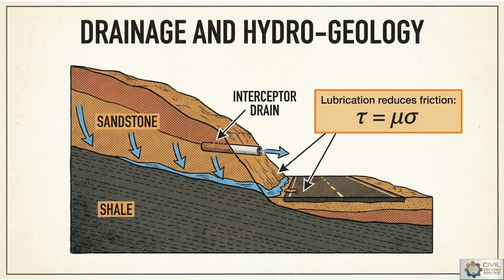So from the drainage and hydrogeological point of view, we can also study the type of rock, just like sandstone and shale, so that the water percolating through the sandstone may show capillary rise or capillary fall action. Shale does not. Shale is a hard rock with reference to sandstone and can't allow the water to enter it, so the water which seeps or percolates through the sandstone layer flows above the shale and below from the sandstone towards the nearby cut region where the road surface is.